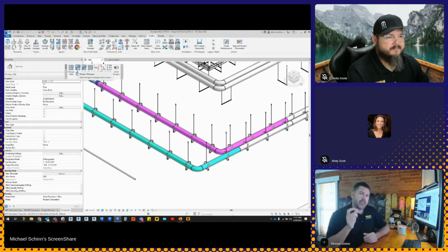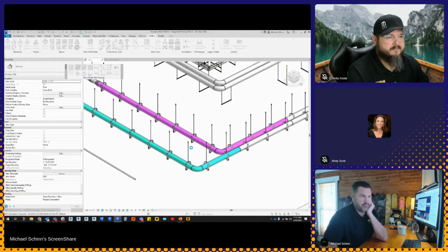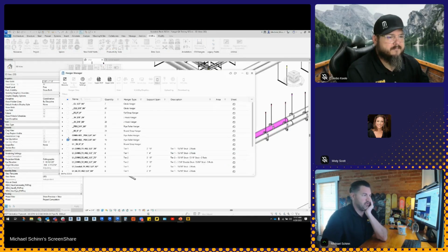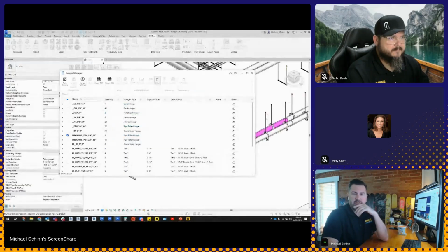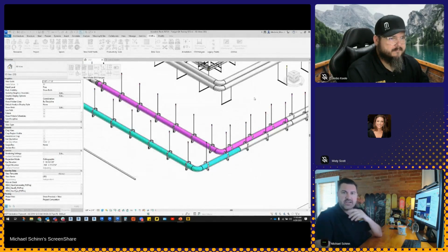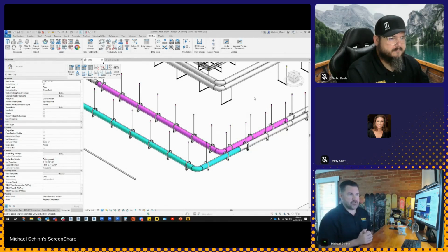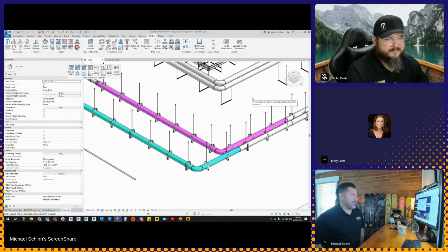So it's a little bit different way of doing it. Instead of having all of your hangers be a part of a spool for that drawing, we now have a drawing automatically here with the full build material for that spool. Here are those 2 spools, those hangers. I need 9 of these for that hanger. And we'll get you a little drawing soon of that little cool clevis and everything. It's a little bit different way of thinking about where we can go with this. Same thing with our packages and everything else too. So we kind of cracked the code on where we can go with Revit. Hopefully that answers a couple of Revit questions, and then I'm done with that.